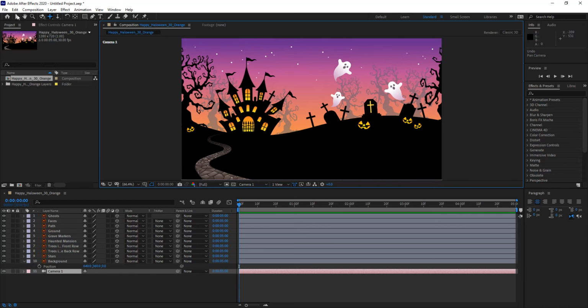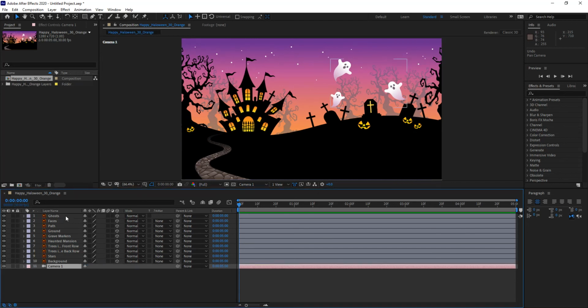Now, one thing that needs to be understood about creating 3D layers is that the layers appear to the camera at the distance at which they were imported. What does that mean? Well, I can play tricks with the position of objects on the screen by taking advantage of a concept called parallax. Parallax is what you see when you are looking at things at a distance versus things that are close to you. Imagine that you're in a train and you're looking out a window. Those things that are far away from the window move slower across the window than those things that are closer to the window. So you can create this effect of having things juxtaposed upon each other visually by making use of that parallax effect.